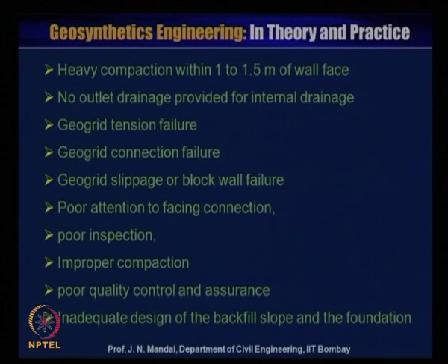Heavy compaction within 1 to 1.5 meters of the wall face. So you have to be careful with the compaction near the facing element. I say that you should use a hand roller which weighs about 75 kg. If you go for heavy compaction, then there is a possibility of bulging. Sometimes you don't know the reason why bulging has formed. So you will require proper compaction, and you should not go for heavy compaction within that zone.